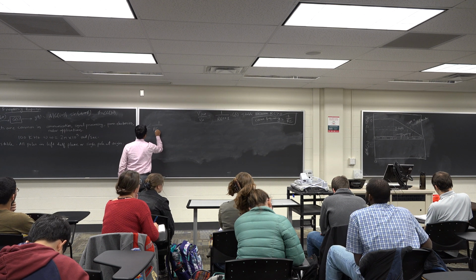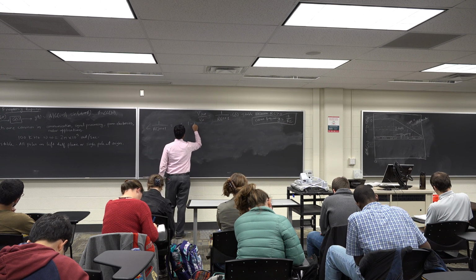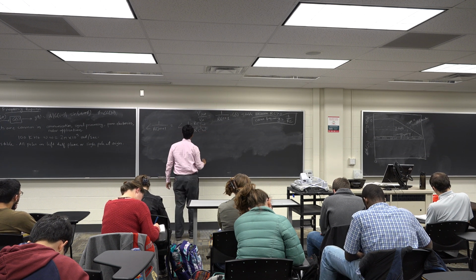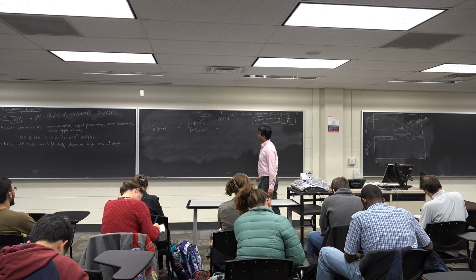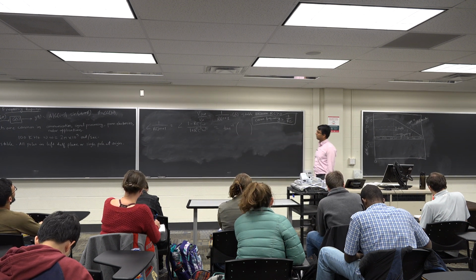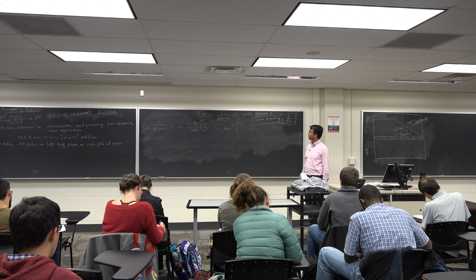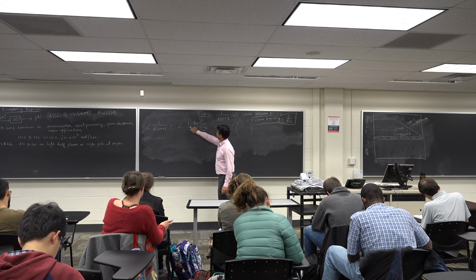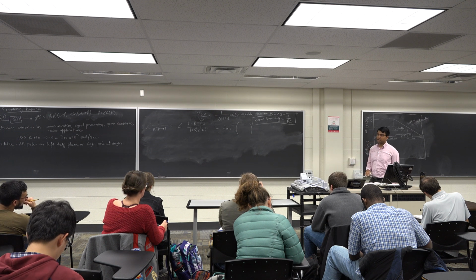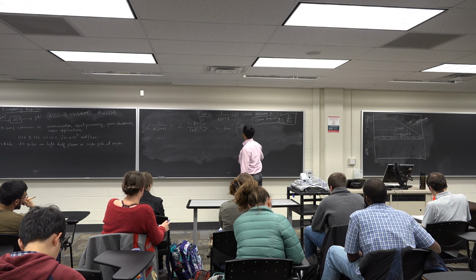Angle of 1 over RC j omega plus 1, which is the same as angle of 1 minus RC j omega over... What is the angle of this complex number? So I have A plus jB in this case. What's the angle of a complex number? Imaginary part over real part. So that's minus RC omega over 1.